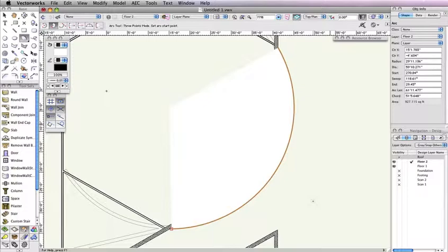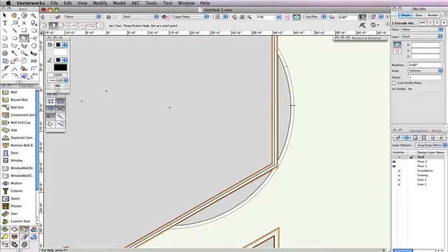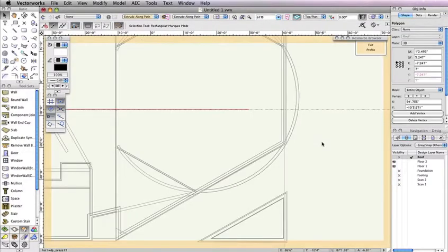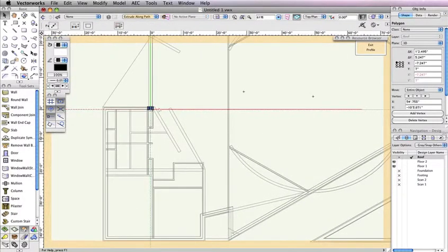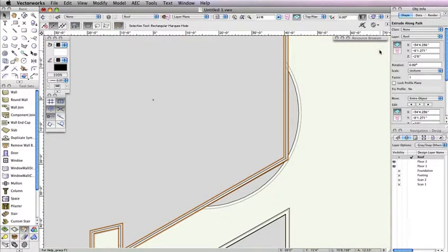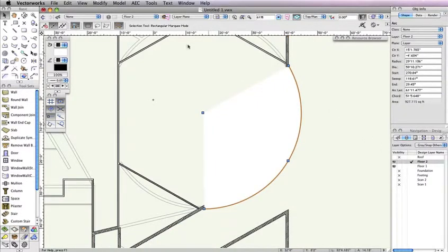To create the flashing cap, you're going to repeat the steps you used to create the triangular walls flashing cap. For the moment, set the roof design layer as the active layer from the view bar. Next, switch to the selection tool. Double-click the extrude along path and choose to edit the profile. With the polygon selected, go to Edit, Copy, then click Exit Profile. Switch Floor 2 back to the active layer and go to Edit, Paste.